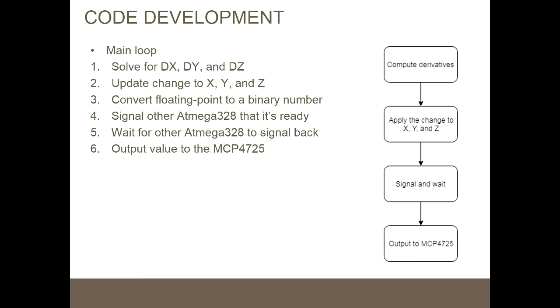So what I did was truncate the fractional part out, which sounds completely opposite of my original goal. You have to distinguish between the two here. When it comes to computing, the goal was to have fractional parts. If you truncate it there, it obviously defeats the entire purpose of this project. But outputting has nothing to do with the computation. Outputting is just interpreting the data. And like I said, the DAC does not support binary fractions or anything of that sort.